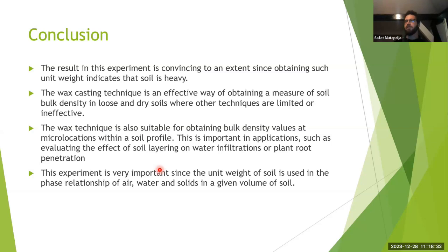So you're not usually calculating how much weight you need to put on soil for the compaction. It usually happens just on the construction site, with the trucks and everything around. That can be different if you have really soft soil, but then you are usually not going to compact it. You're going to mix in cement or use some different techniques to actually get strength. Or we're going to use huge dynamic compacting machines, as you maybe saw somewhere on YouTube.